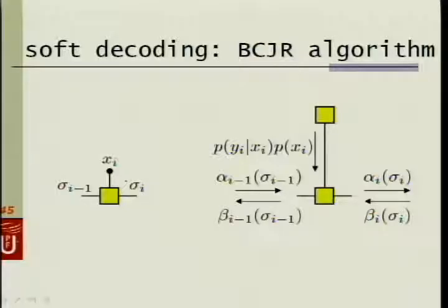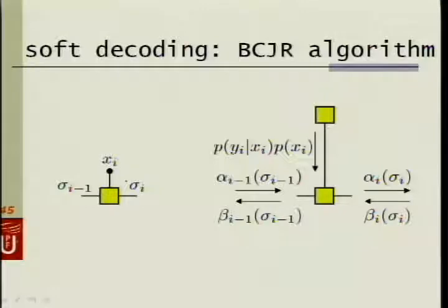And it's interesting, if you ever have the chance of looking through my book, I have derived the BCJR algorithm in the standard way, the historically original way, and using the sum product algorithm. Well, the first derivation takes 3 pages, the second derivation takes 3 lines, which means that once you have understood the sum product algorithm, which is conceptually very simple, as we have seen, then you have a possibility of understanding a number of other algorithms that are apparently more complex. Actually, the original version of BCJR looks more complex, but interpreted as a sum product algorithm becomes really simple.